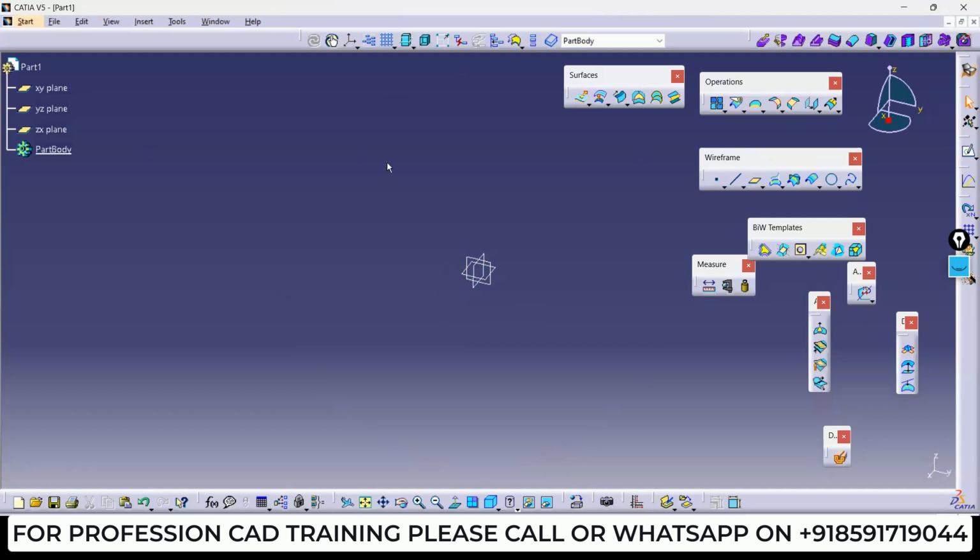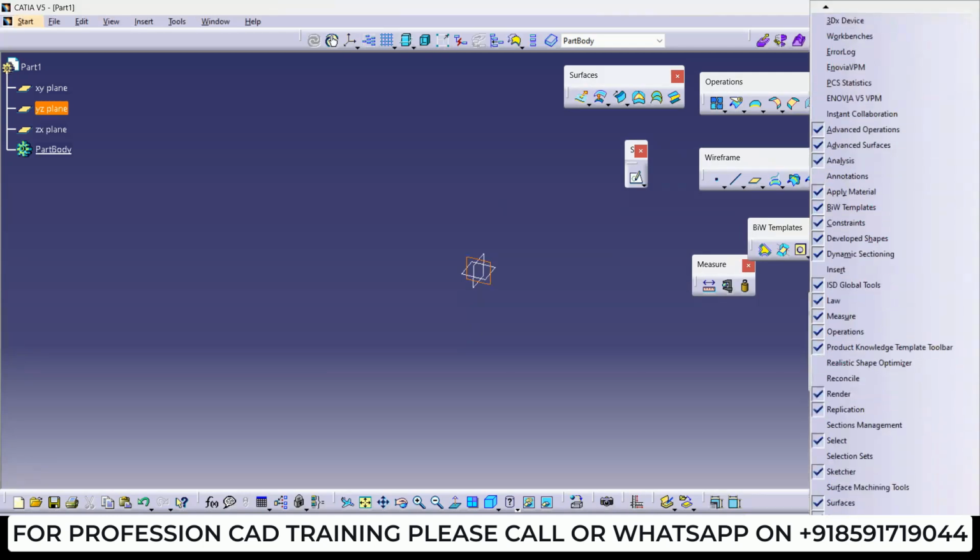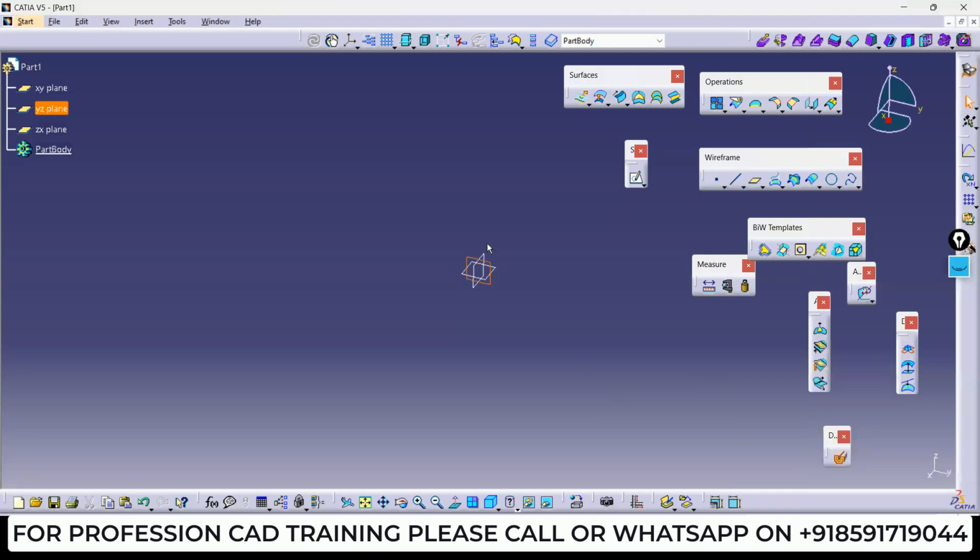So if you want to shift into the sketcher, first you need to click on the plane, any plane, and here you can find the sketcher toolbar. If you are not able to find it, you can right click and find it at the bottom also. This is Sketcher is on. If it is not on, you can click on this so that the workbench toolbar will be automatically on. So you can select any plane.